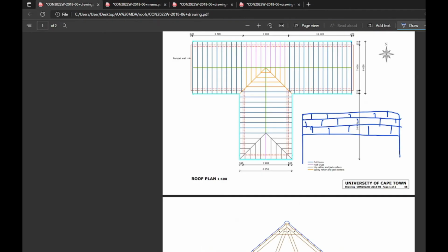Galvanized sheet steel. And the interface where roof, let's just say this is a mono-pitch roof to make my drawing easier. And it's sometimes stepped, and you'll see it in public as a step flashing. It needs to be parallel with earth, so stepped. It runs down, right?